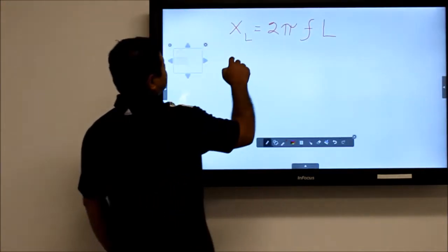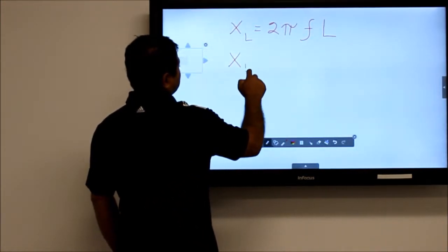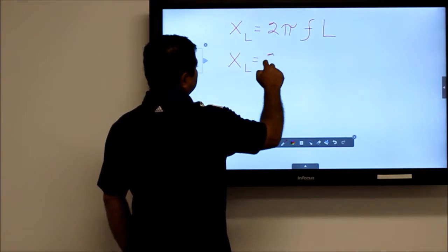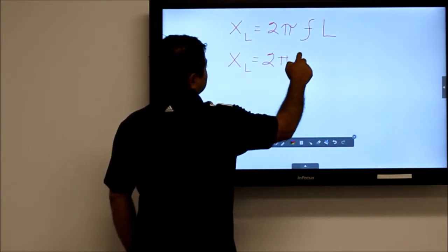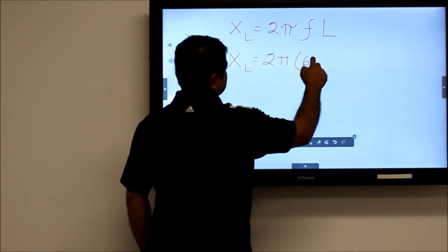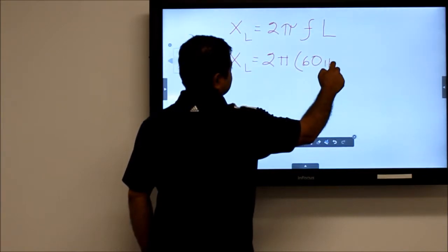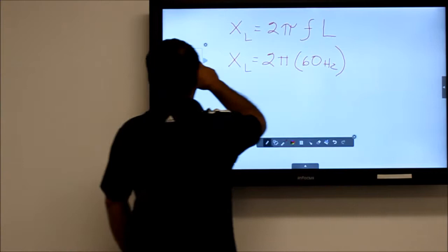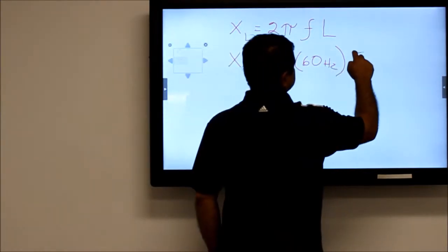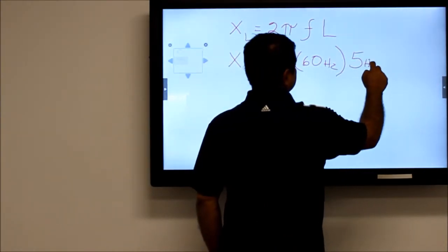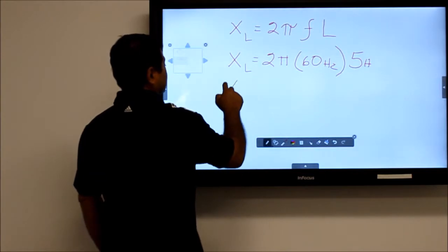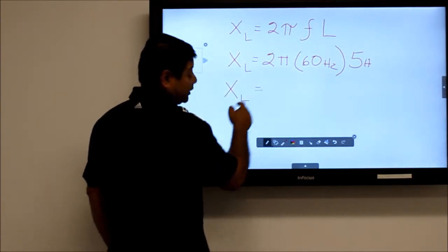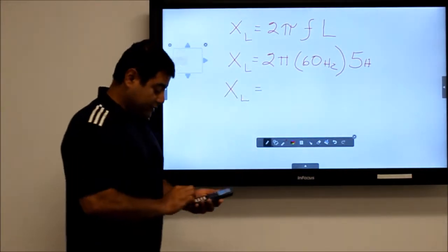So let's do that. I have the inductive reactance equals 2 pi times the frequency, which is 60 hertz, times the inductance, which was 5 henries. Alright, so now go ahead and do it with me so you can get some practice.